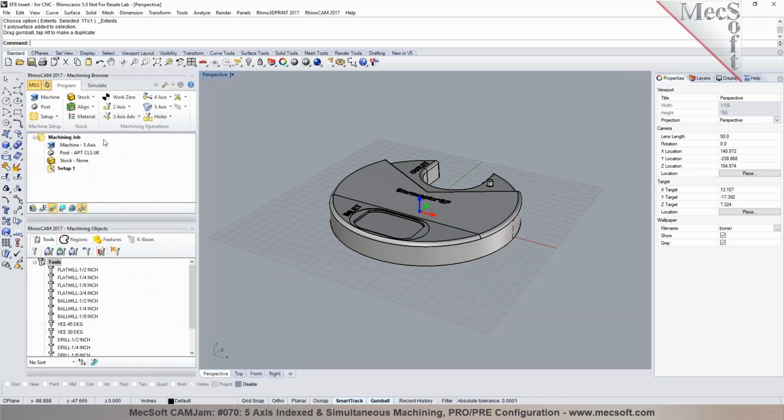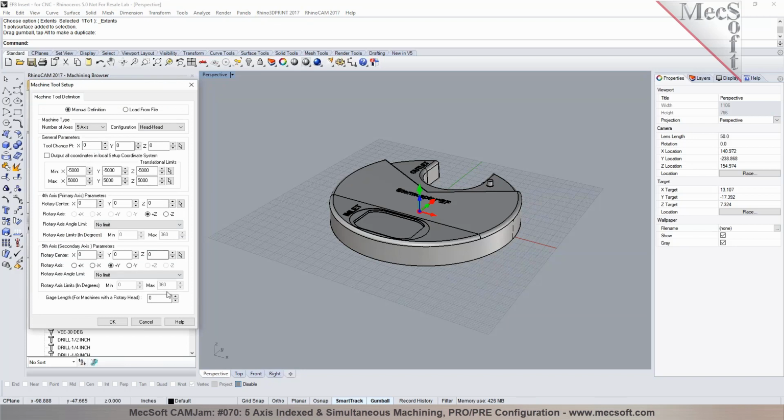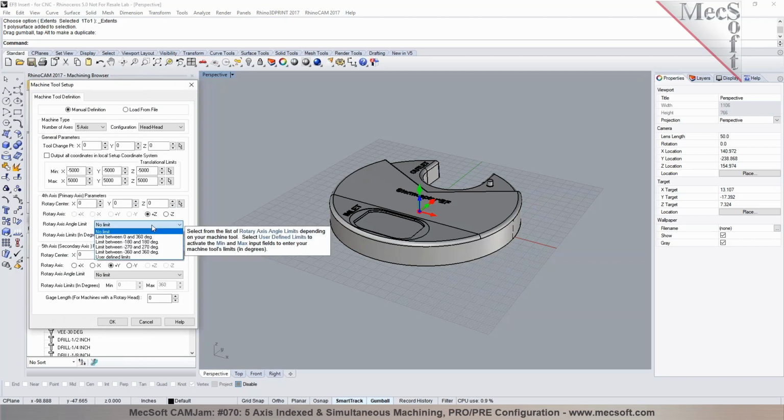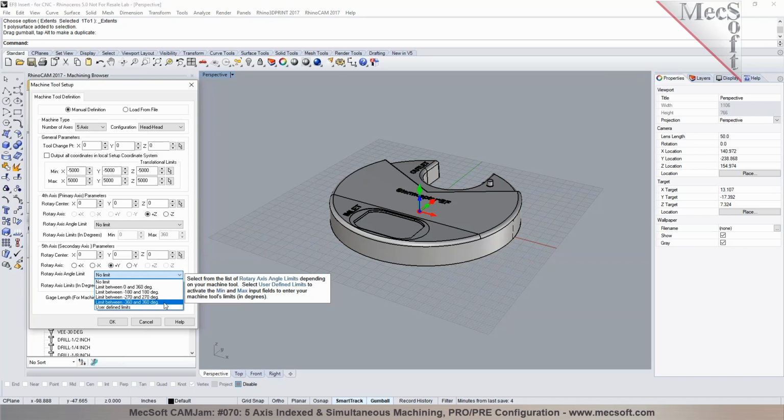And all of these settings that you put in can be saved into a knowledge base, so when you're working with other parts, you don't have to go through the process of defining it in each step. Right. Okay? You can also establish your rotary axis limits for primary and secondary. So primary could have no limit, the secondary could have like a -2 to +110 or whatever the angle limits of the secondary or the B axis are, and can be specified right in here.